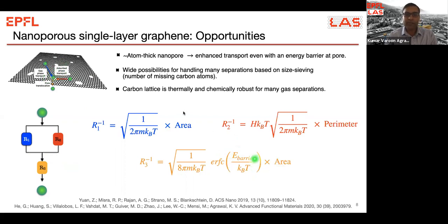And this barrier is dependent on the relative size of the molecule and the pore. This is why this really excites us, because there is a wide possibility for handling many different separations based on size sieving, if we can tune the size of these pores to the desired pore size distribution that is suited for a given gas separation.